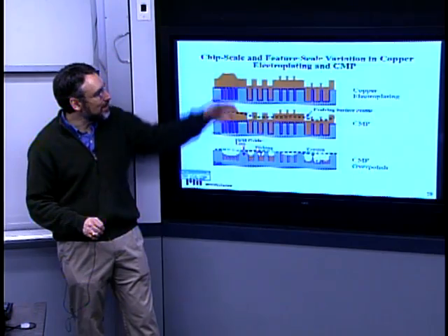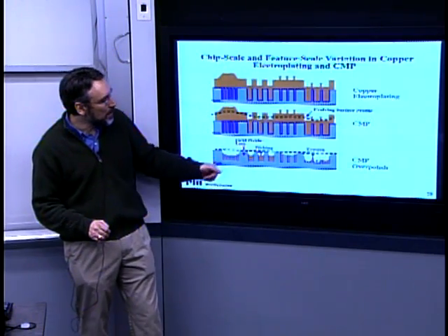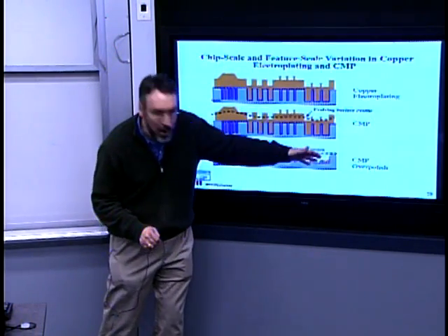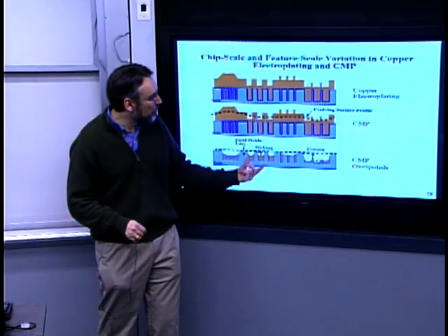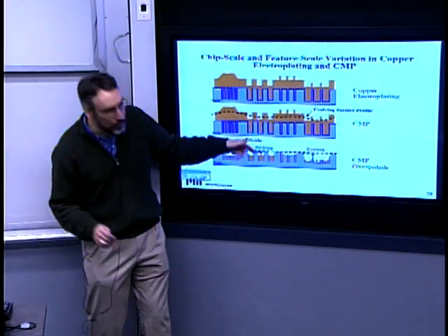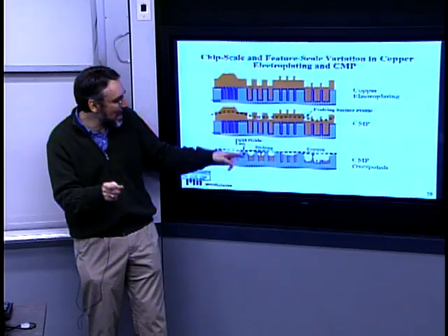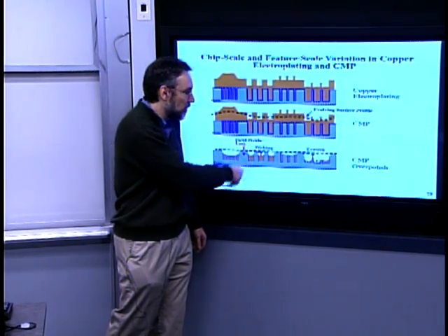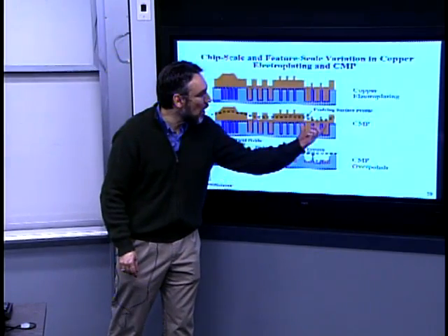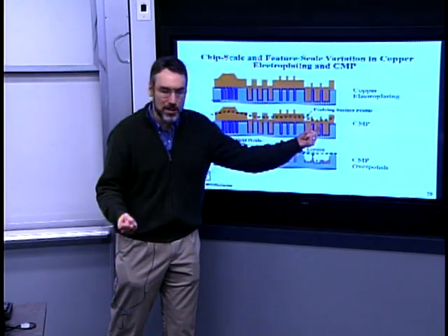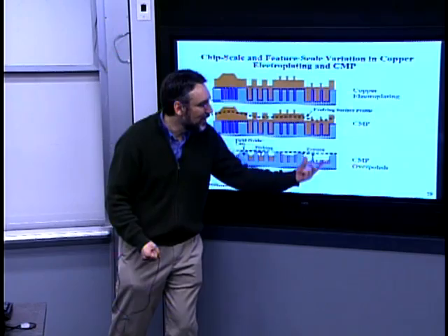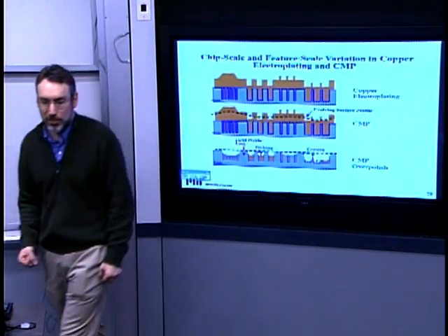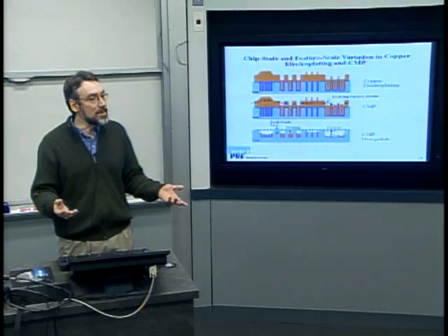But it also has a geometric imperfection arising from over-polish, where big, fat, wide lines, the polishing pad, that polyurethane pad, actually digs down in and over-polishes certain features. And in regions where you've got a lot of copper and very little hard supporting oxide, it actually erodes down appreciably. So these are some systematic effects.